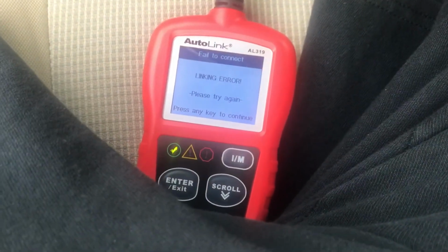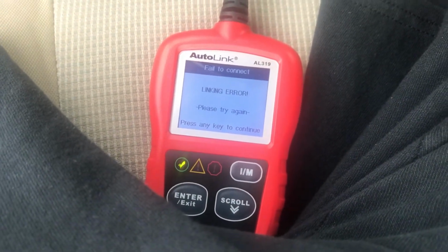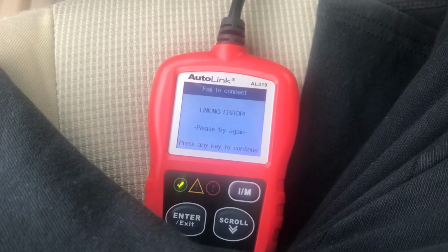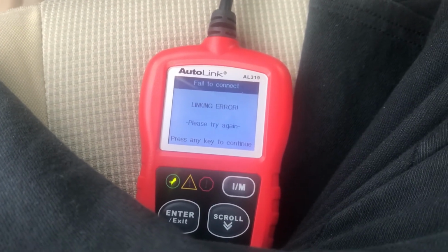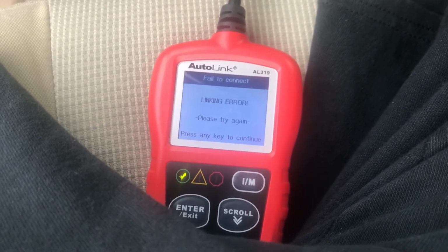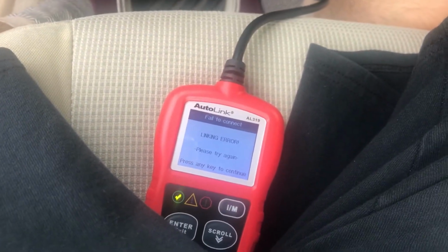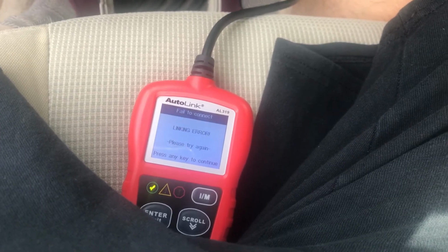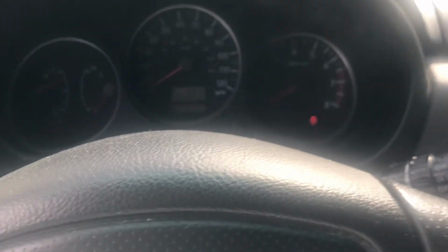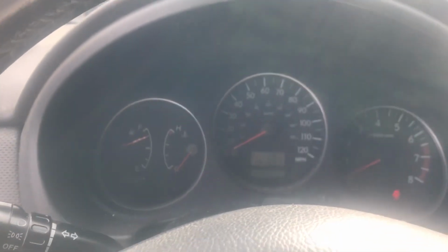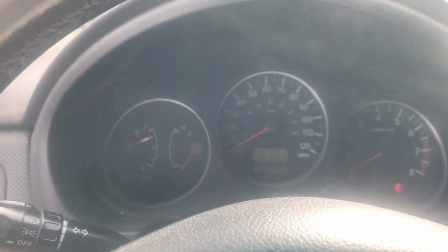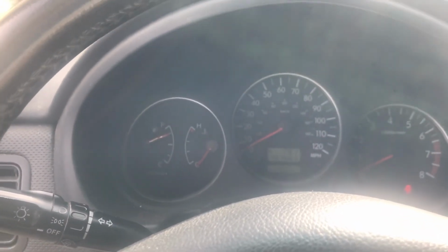Alternatively, it could be a malfunctioning O2 sensor, but unfortunately it's probably not usually the case, but it's always nice to check the cheap stuff first. The other thing that I know a lot of people talk about is leaks in the intake. So check your intake vacuum hoses and manifolds and all that stuff, and make sure all those things are tight. That can also be another cause of the P0420 error, or sometimes it's called a P0430.